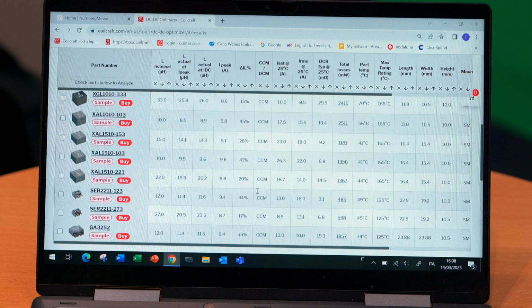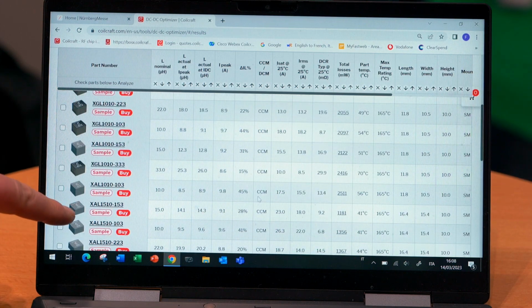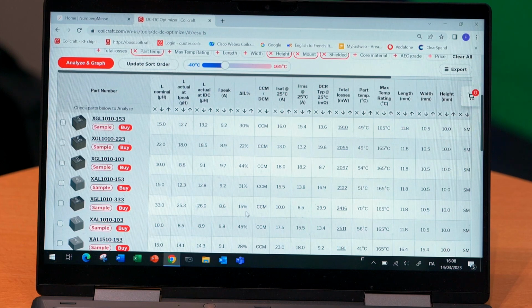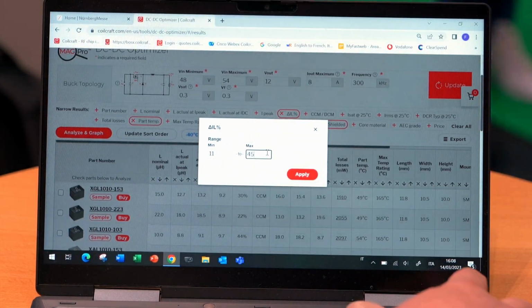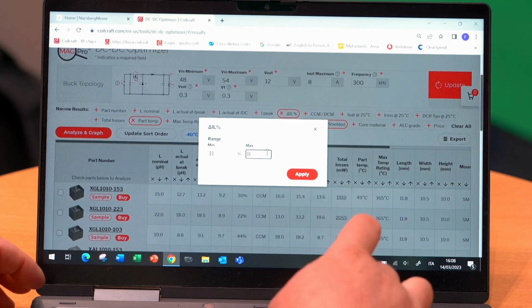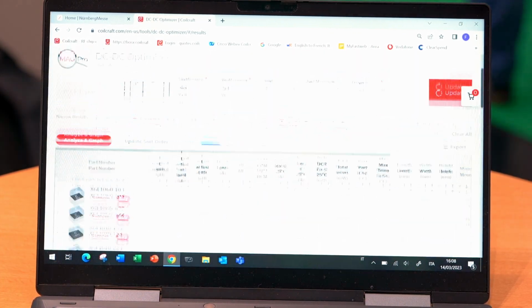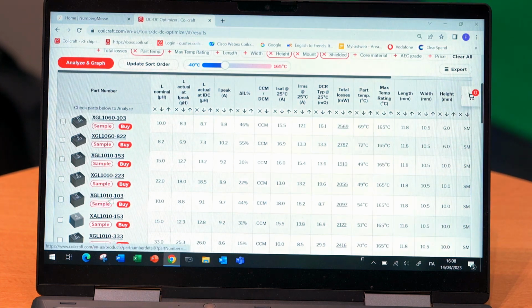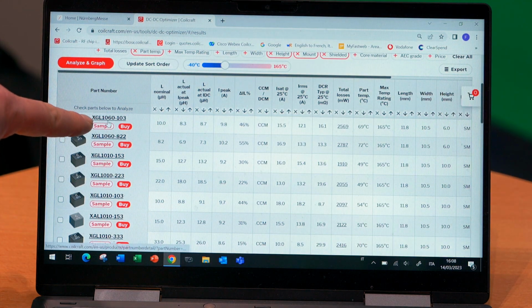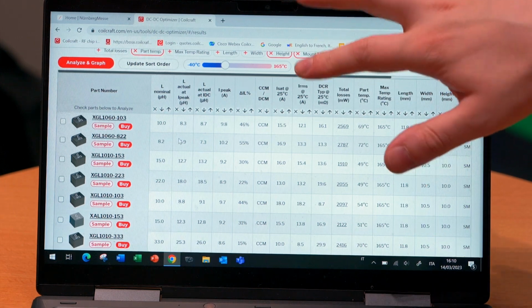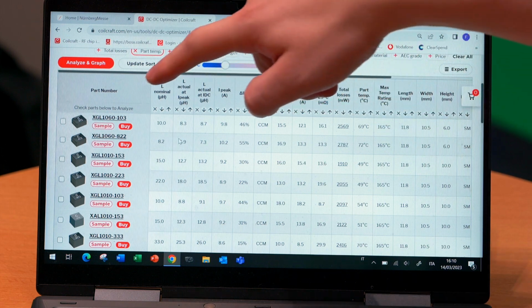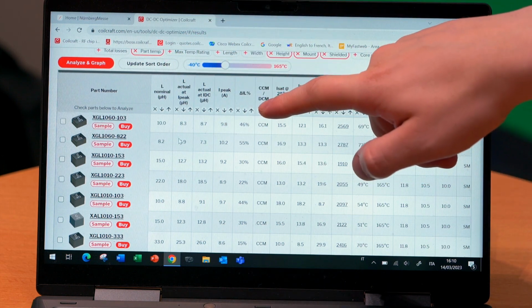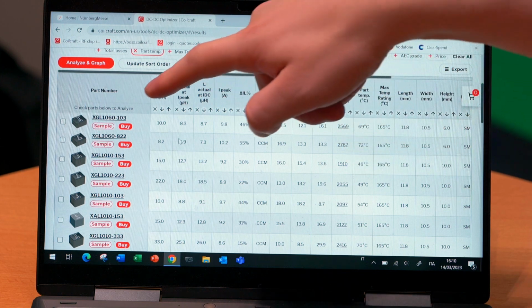As you can see, we have the 10 millimeter, we have the 15 millimeter. Maybe we can go even lower. So let's review, for example, this, and instead of saying 45, let's put double, 80. What happens? Now you see appearing also a 6 millimeter tall part. So what we're basically seeing here is that you can sacrifice some aspects of your design to improve others. So for example here, we make the ripple worse, but we can get a smaller part.